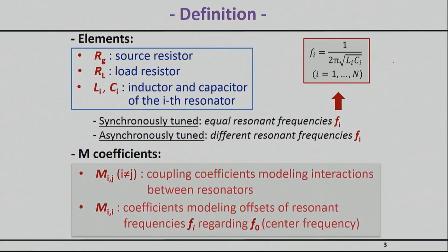All right, so this is essentially a reminder of what the symbols mean, but there's also some new information that is used quite commonly in the filter literature. We use the terms synchronously and asynchronously tuned filters to signify whether we're tuning all resonators at the same frequency. When you have a synchronously tuned filter, your resonators are all at exactly the same frequency, whereas if you have resonators at different frequencies, that's an asynchronously tuned filter. Both are possible, and they both have pros and cons.